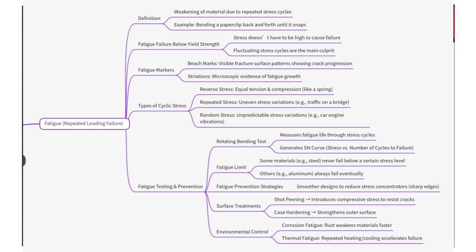Okay, so let's talk about how these fatigue cracks actually form. Fatigue cracks almost always start at the surface, and often at points of stress concentration. Remember those microscopic flaws and macroscopic defects? Like those little scratches, sharp corners, the threads on a bolt. All of those things can act as stress amplifiers. And those are all on the surface? They are, and they make those areas more vulnerable